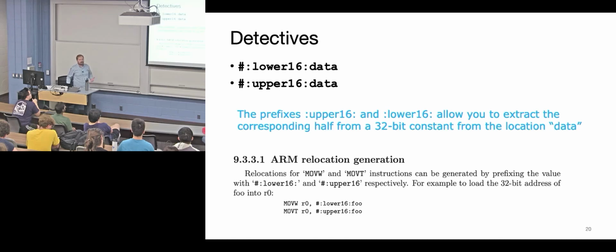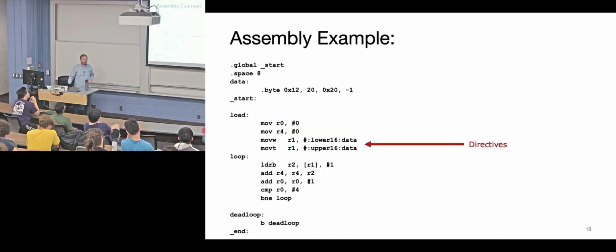Yep. So when you're moving to a register, like move R0, 0, you're only moving 16 bits into R0. Think about the immediate: you can't put 32 bits in there. So it's going to pad. The move command will put the 0 and put all zeros in the rest.